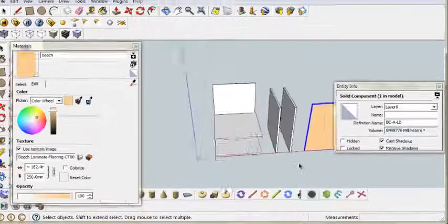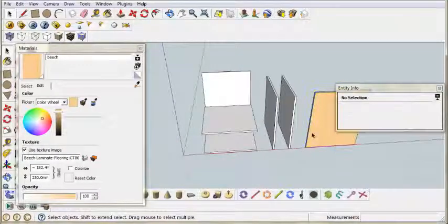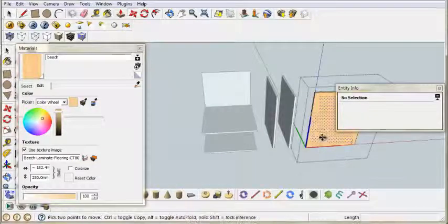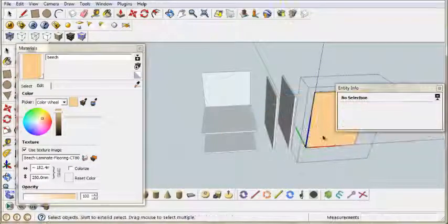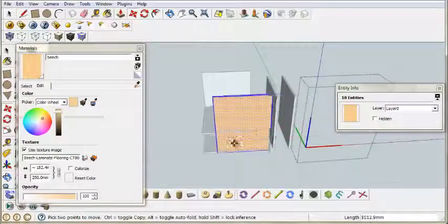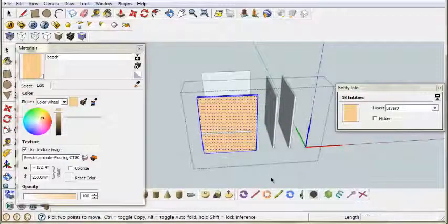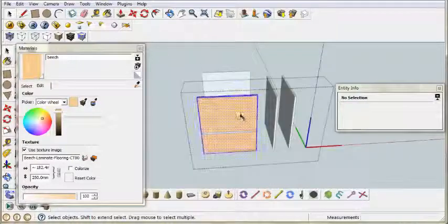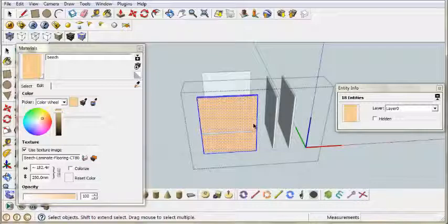Now why are we turning them into components, by the way? What it does is it actually lets you move your components relative to each other. Oh, sorry. Make sure when you're moving, you highlight 3 times, then click them 3 times, then move it. When you move your components against other components, it won't give you the same bug that happened a while ago. You can actually click them while they're intersecting. So the next time you make a project and you want an entity to stay as it is, just create it as a component, and other entities won't be bothered by it.